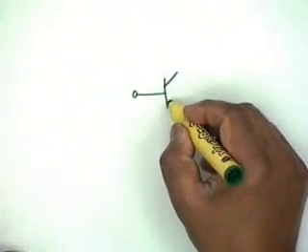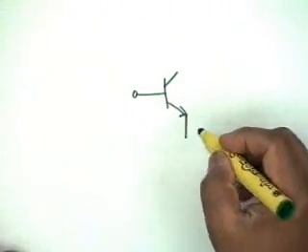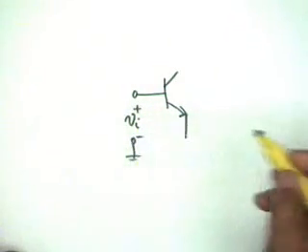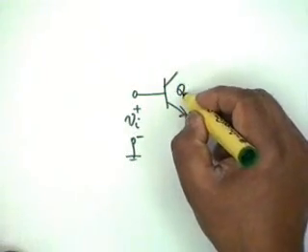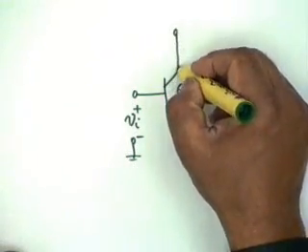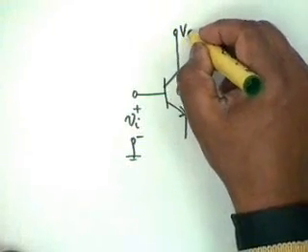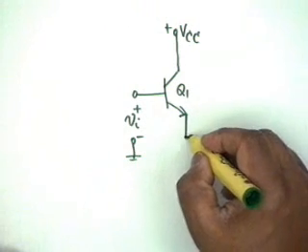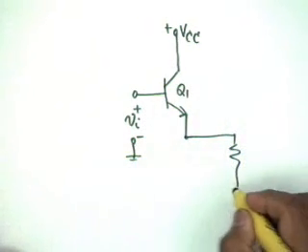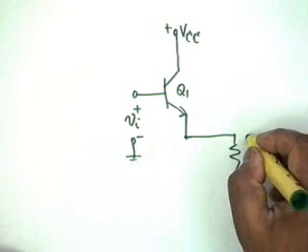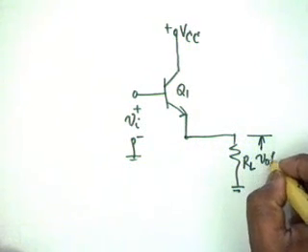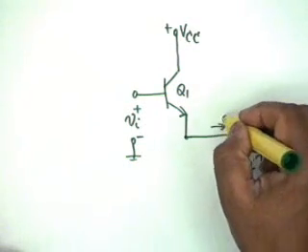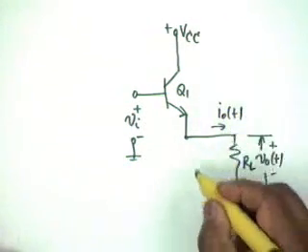that is, we used the minimum number of resistors and as many transistors as is required. We have a VI plus minus the main transistor Q1, which is operating in the emitter follower mode, that is, the collector is connected directly to plus VCC and this emitter goes directly to the load RL. The voltage here is V0 of t. We have gone back to the time domain, and the current through this is I0 of t.